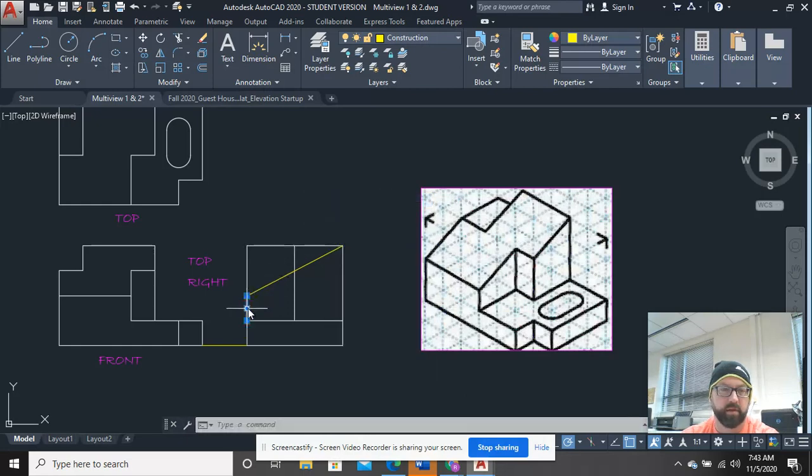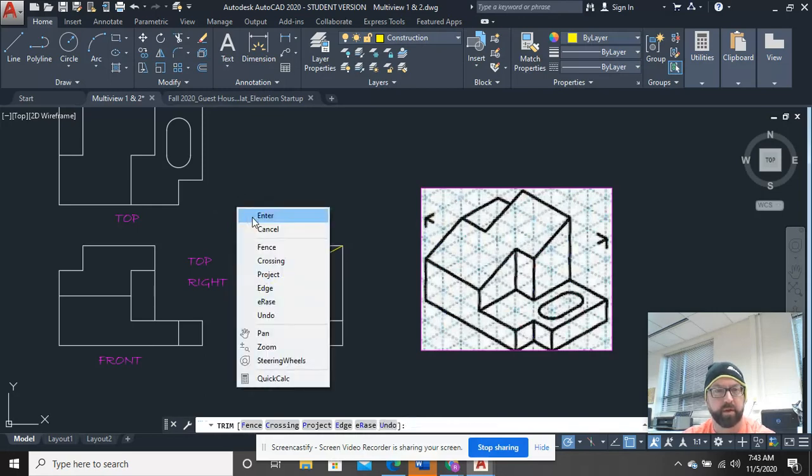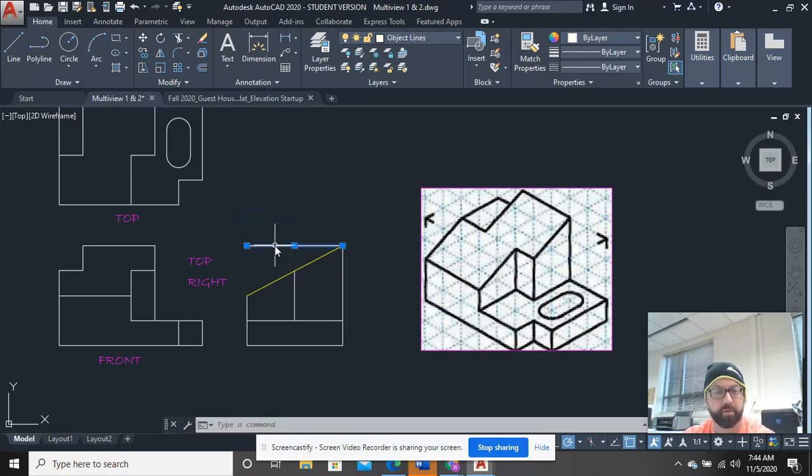Okay, this line goes away. So does this. What happens next? Trim, TR spacebar. I can grab all of this. When you're selecting stuff, people are still having a little trouble. When you select multiple objects, if you go from right to left, it'll grab kind of goofy stuff. When you go from left to right, when you click once and go bottom right to top left, it'll work a little bit better for you, okay? And then this is on the wrong layer, right?